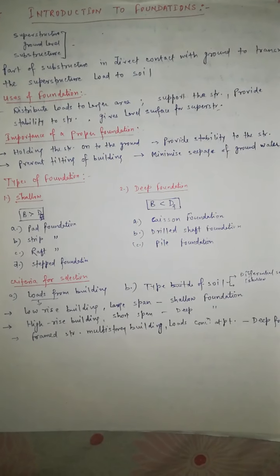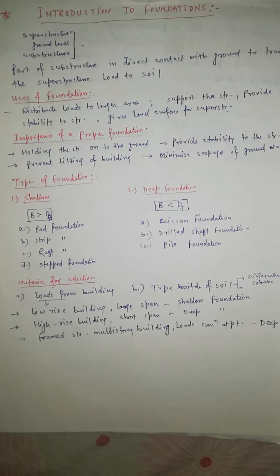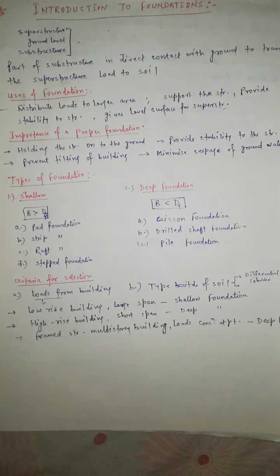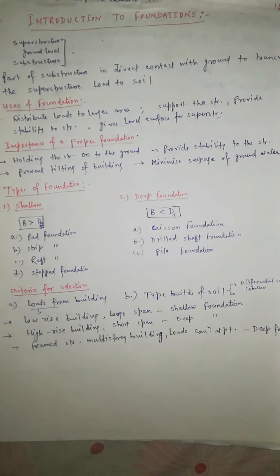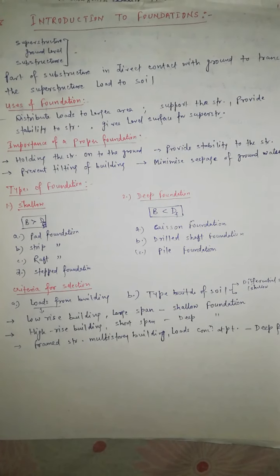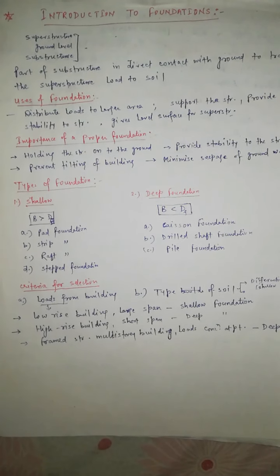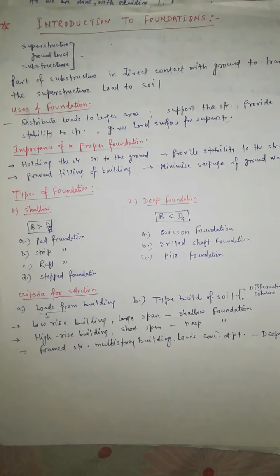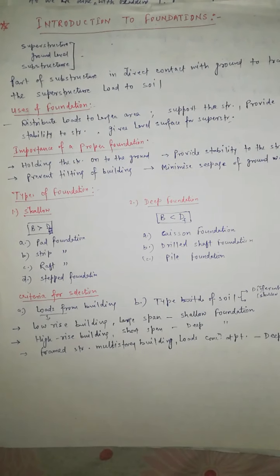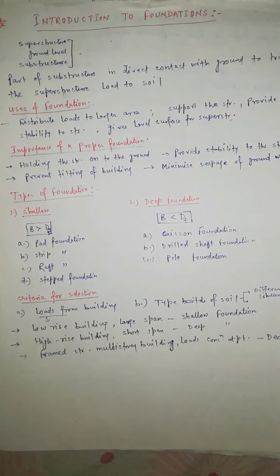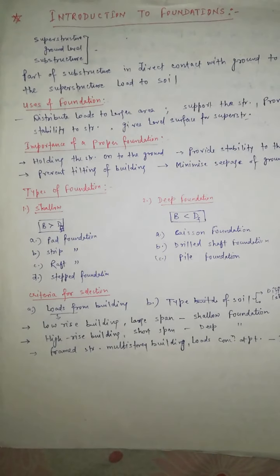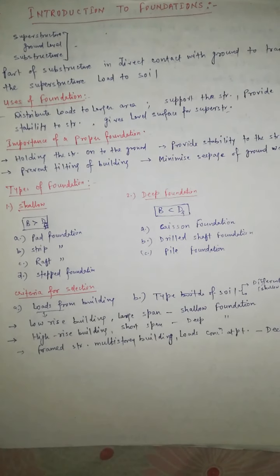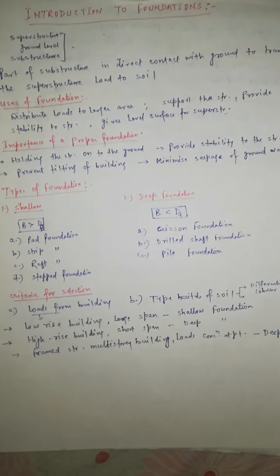Now, what is the objective of foundation design? Basically, the objective of foundation design is to provide stability to the building and increase its serviceability. Now we will learn the basic design procedure in foundation design. First is assessing site condition. Here the soil investigation report is prepared, and soil strength and bearing capacity are measured.